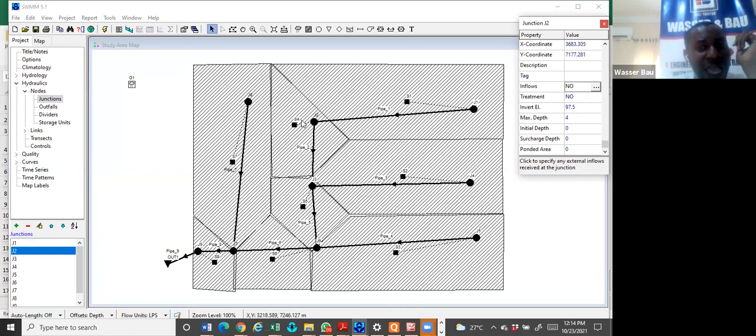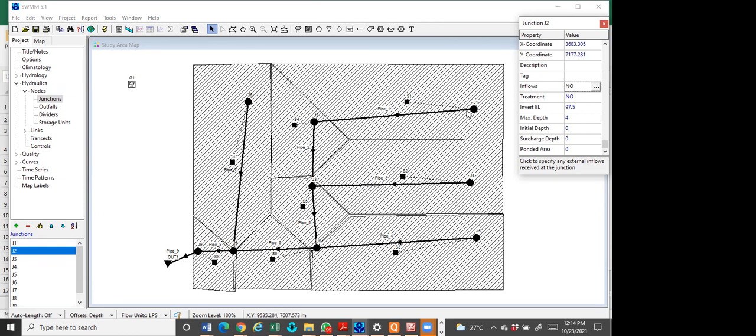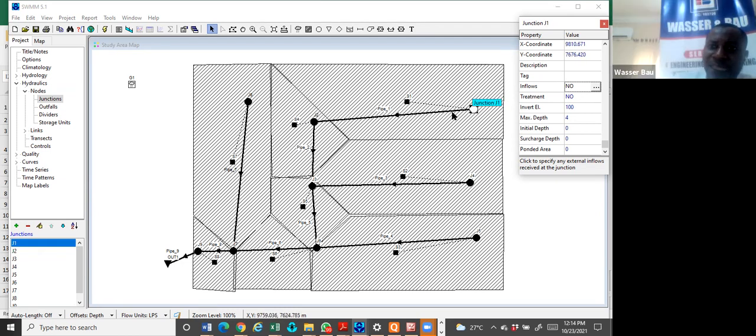That's what it means. After half a kilometer, the slope has gone down by about 2.5 meters. So if the spot height here is 100, at a 0.5 slope, which is 0.005, I have come to 97.5.